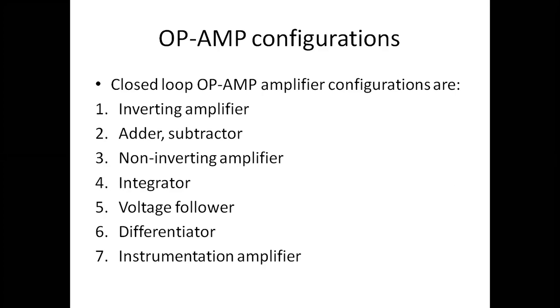If you see, we can use op-amp as integrator, we can use op-amp as inverting amplifier, we can use op-amp as adder, subtractor, we can use op-amp as non-inverting amplifier, because we have seen if we are supposed to give positive input, we can give positive input at the pin number 3. And if we are supposed to give negative input, we can give at the pin number 2, which is the inverting terminal. So, which will give us the inverting output.